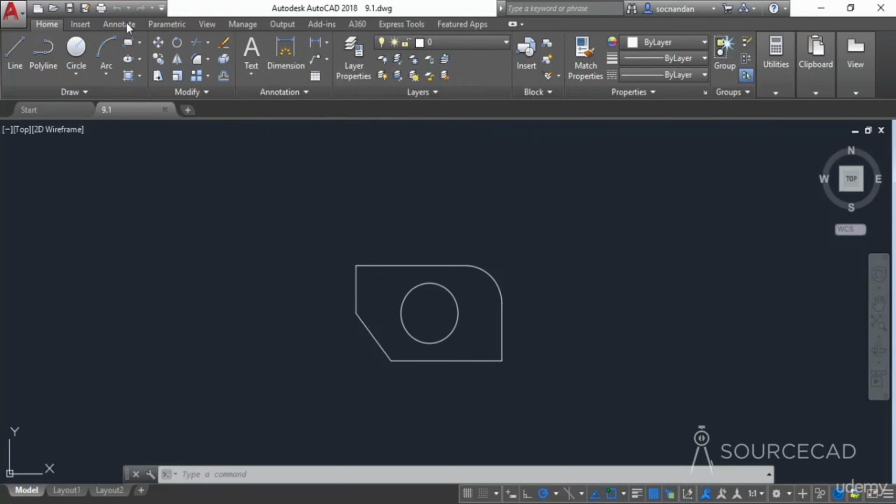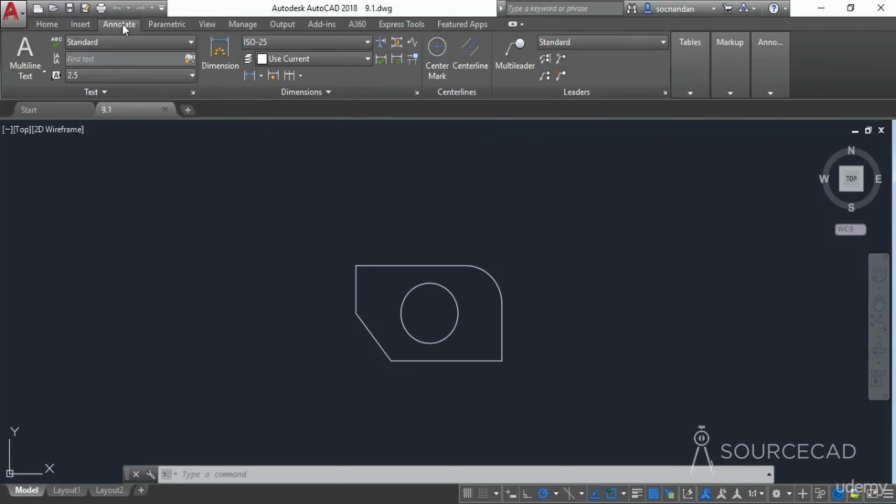Apart from that, we can also make dimensioning and other annotations from this annotate tab. When you go to the annotate tab, you'll see many different panels like text, dimensions, center lines, leader lines, tables, markup, annotations. These are different panels which can be used for adding different kinds of annotations. And here we have the dimensioning panel which we will use for this lesson.